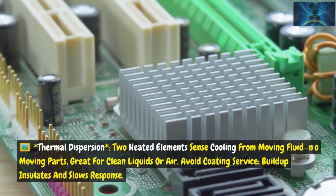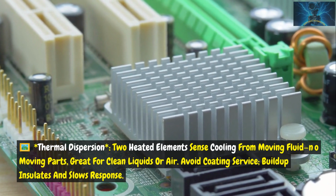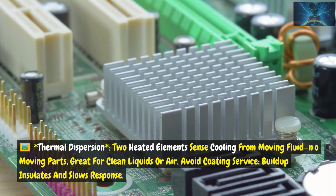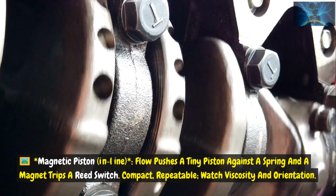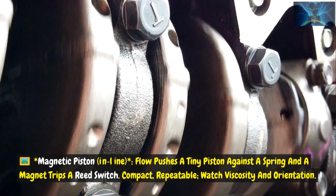Thermal dispersion: two heated elements sense cooling from moving fluid. No moving parts. Great for clean liquids or air. Avoid coating service; buildup insulates and slows response. Magnetic piston, inline: flow pushes a tiny piston against a spring and a magnet trips a reed switch. Compact, repeatable. Watch viscosity and orientation.